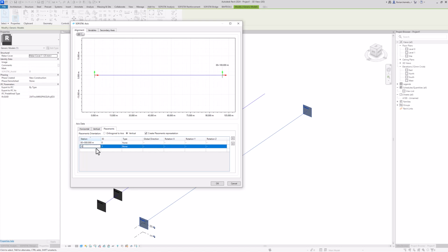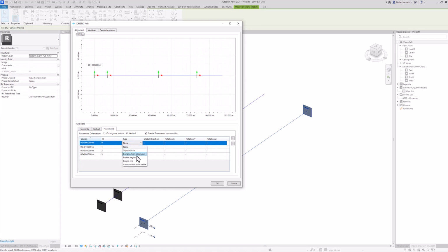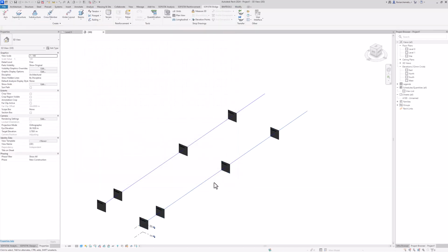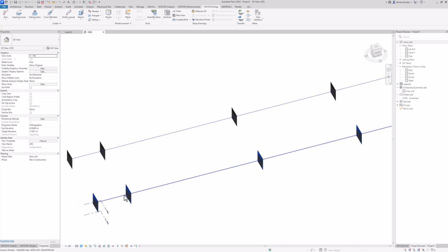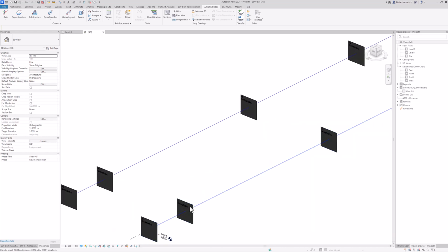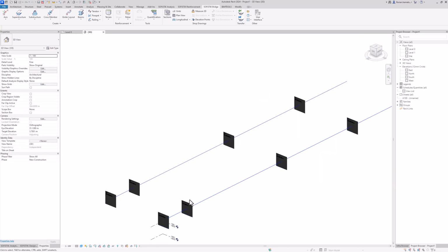And I can just very easily change the first placement with ID 1 to 10 meters, create a new one at 50 meters, and a new one at 80 meters. I change the type to axis in the beginning and support. I click on OK. And now I do have an externally input axis, which fits the original requirements of our manually input axis.